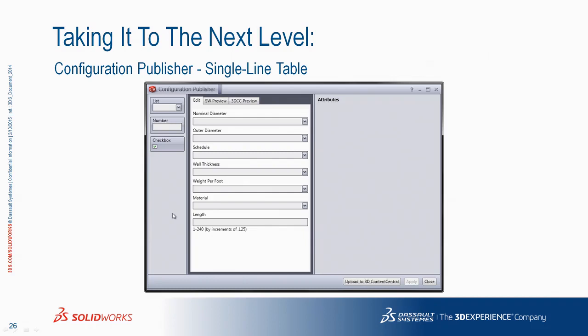What's the use of the configuration publisher? The use of it is if you have 20, 30 different users of the software, or just a few who don't understand configurations, you got it all locked down inside of this. They can't screw it up at that point in time. Nobody can go in, like I say, and create a pipe that's 3 1/16 of an inch when 3 1/8 is the limiting factor at that point. So you're basically just controlling the environment at that point. That's really what it comes down to.